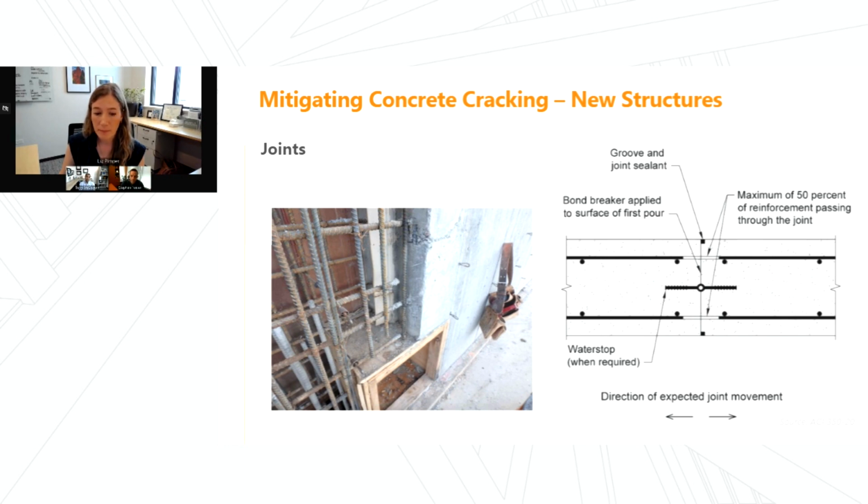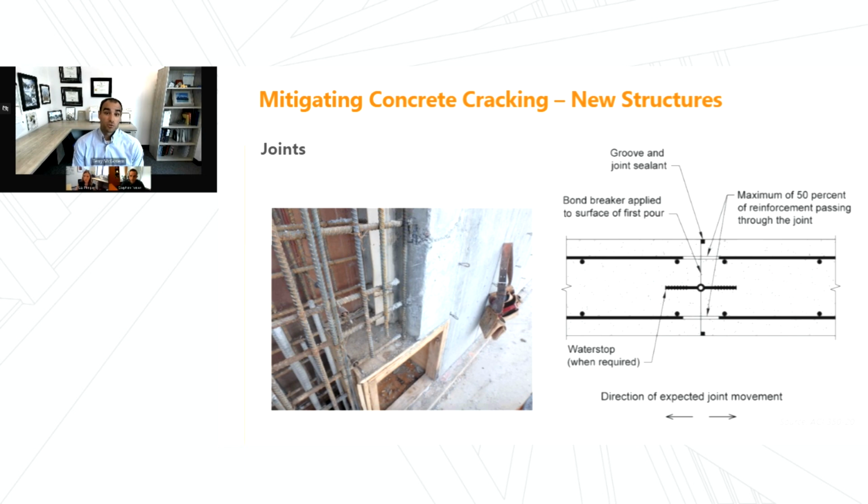Well, the addition of steel isn't trying to eliminate shrinkage cracking. It's trying to distribute it. So you could reach a situation where potentially you've mitigated it appropriately to where the stresses that are produced inside the concrete member don't actually result in a crack, or you could result in cracks that are so fine you're not even seeing them, or you're certainly not seeing them highlighted with leakage. So it's not that they're preventing the shrinkage, it's that they're mitigating the problems that come as a part of that, the cracking.